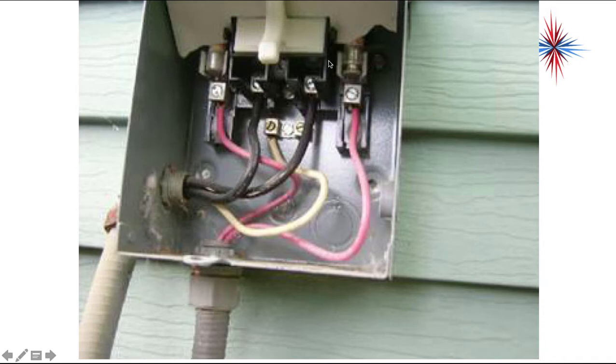Again, pull out type here, there might be fuses hiding up behind it. Note how these are connected. Okay, you have voltage coming into it down here, goes to L1 and L2, and then you have L1 and L2. Don't connect L1, L2 to one side or you'll have a direct short.